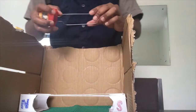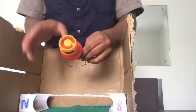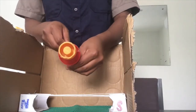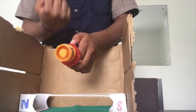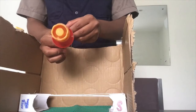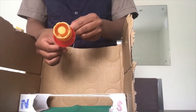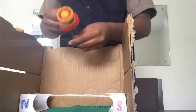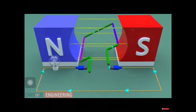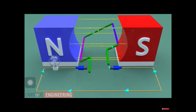So, just using the little piece of the armature with the conductor. Consider the case of an armature rotated in a clockwise direction and the conductor left moving in an upward direction. As the armature completes its half rotation, the direction of the movement of the conductor will get reversed downwards. So the direction of the current will be alternating due to the magnetic forces from the permanent magnets.